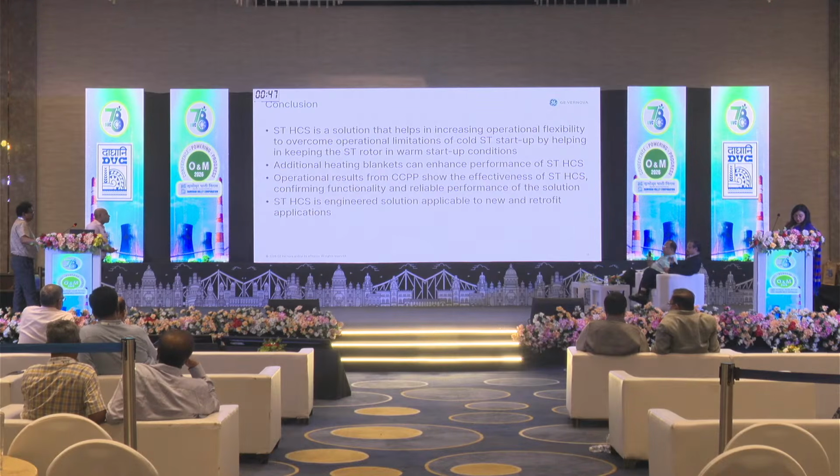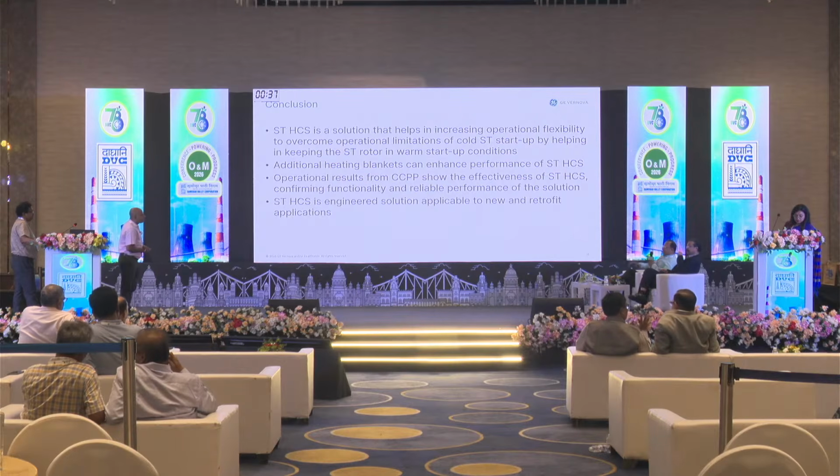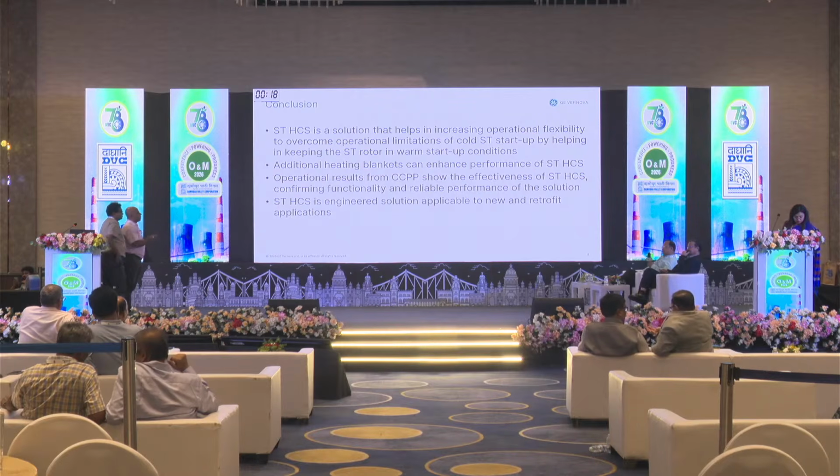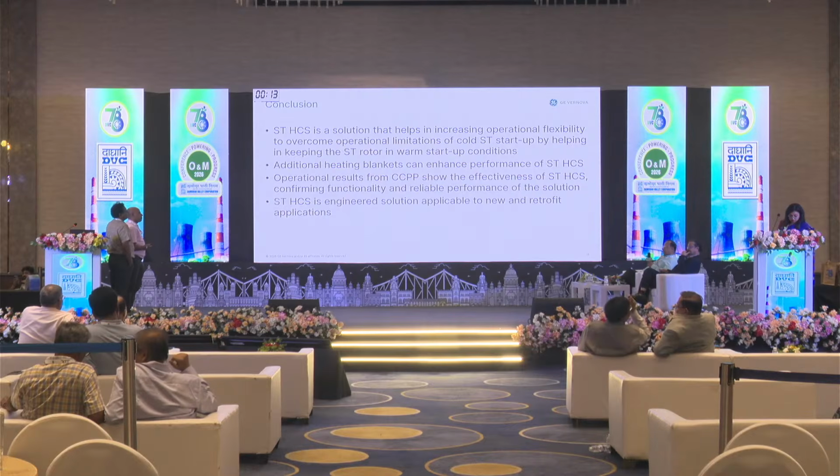Does it have any effect on the auxiliary consumption, because you are using a heating coil for the air heater? Sorry, sir, come again. Auxiliary consumption of the power plant may also increase? Sir, actually, the heaters which we are using are electrical heaters. The power of the electric heater is not too much, sir. So the expenses for running these heaters are really negligible with respect to the cost which we are incurring for the cold start of the power plant. Cold start as well as the corresponding auxiliary.